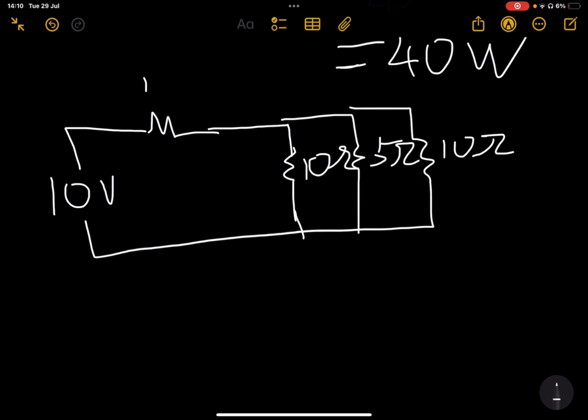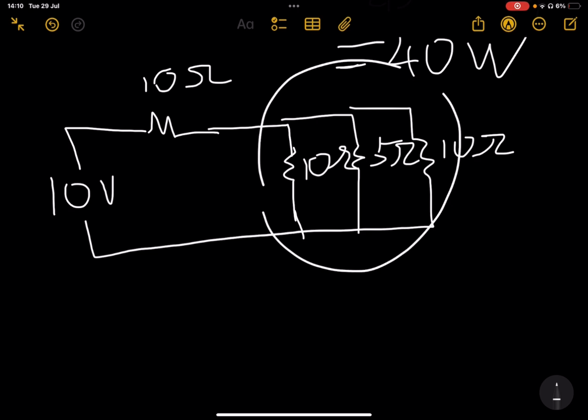And we add a 10 ohm resistor here. Right. So essentially what will happen here is the voltage will drop over this 10 ohm, but only to a certain degree in proportion to this over here summarized as another series resistance. This entire piece of the circuit is essentially equal, as seen by the source, to 2.5 ohms.